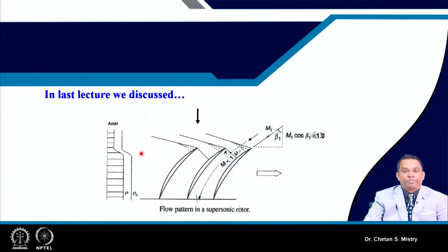Such kind of diffusion or pressure rise we can achieve by having this kind of shock mechanism. Up till now, when we were discussing the axial flow compressor, we used to say this shock creates trouble, and that is the reason we were looking to avoid the flow going supersonic. Once researchers realized this can be taken as a benefit, it attracted attention towards the development of new aerofoils.